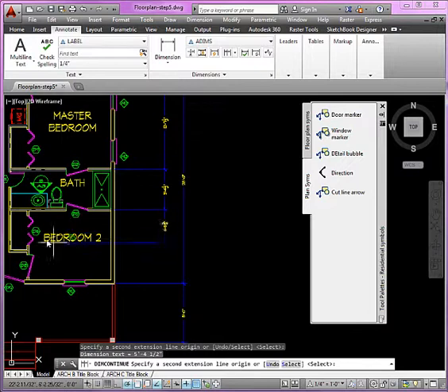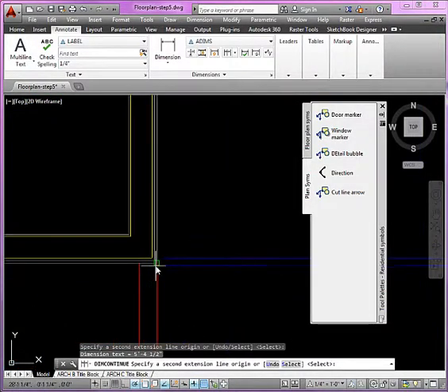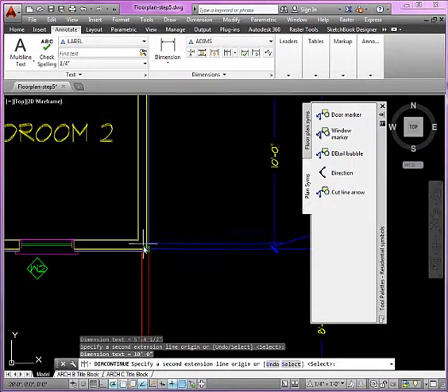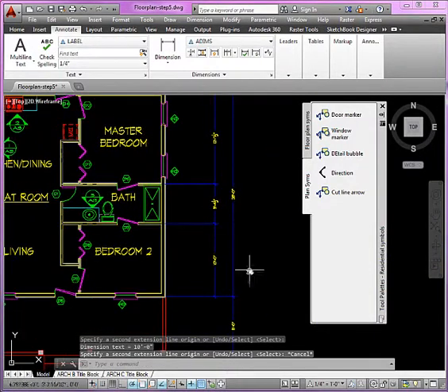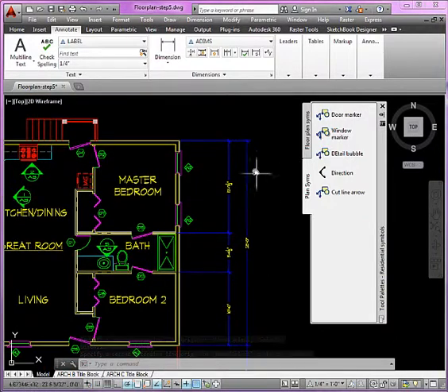And you can see I have other walls here too. Now for those, I'll show an interior dimension line. Okay, but here only the walls that come and connect with that exterior face on this side, right? You'll have to take a look at each side of the floor plan. You definitely want to minimize any kind of duplication. So here I finish on this side, escape. So you can see these dimensions are all aligned right here. The problem is going to be, for clarity, to make sure that the spacing between this set, and the final set is all equal.